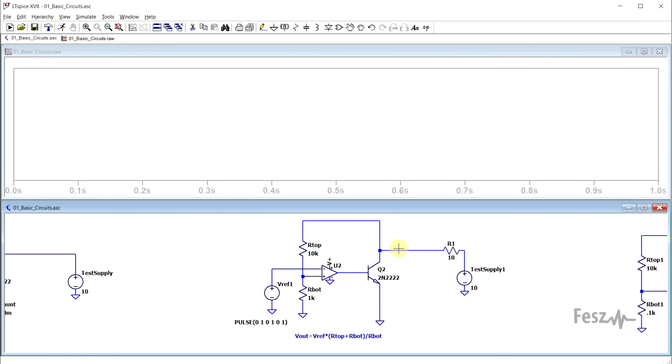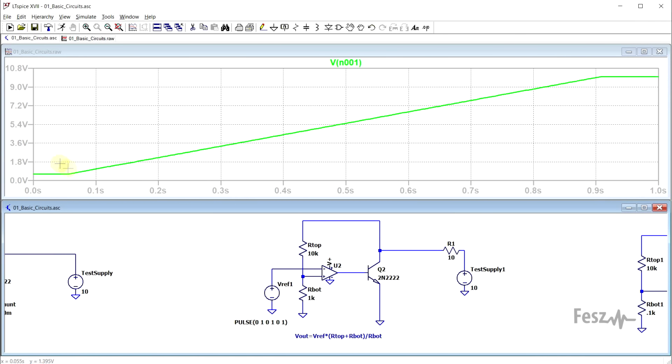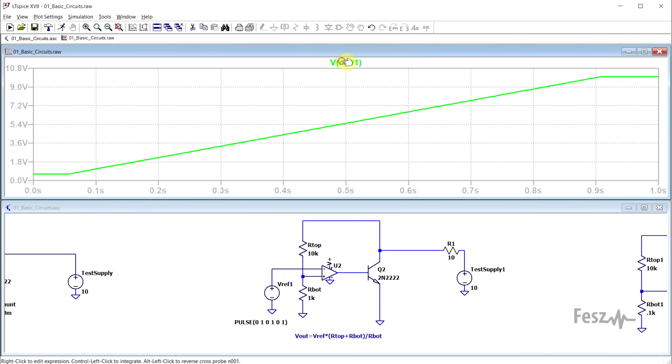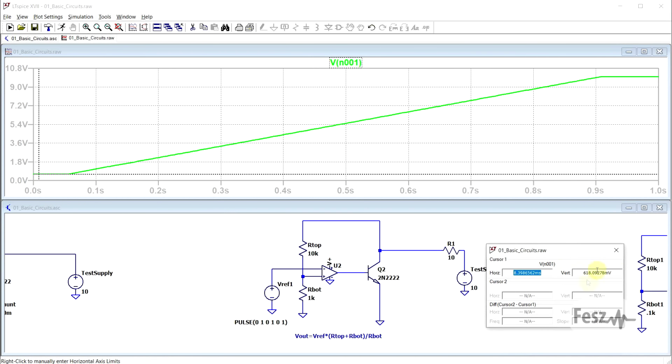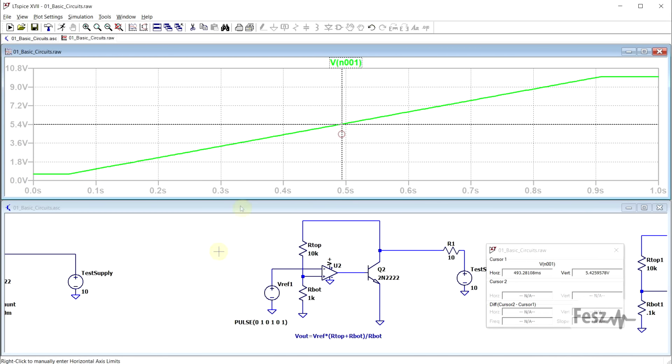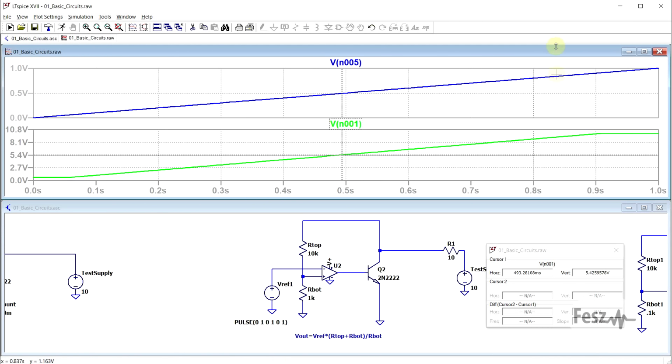Now, if we look at the output of the circuit, there seems to be some sort of issue right at the beginning, so the load doesn't stabilize from 0, but rather from around 0.6 volts, and this is to be expected since the transistor that I used has a non-zero collector-emitter saturation voltage. So this might have been a bit better with a MOSFET, but to some extent you will still have this issue.